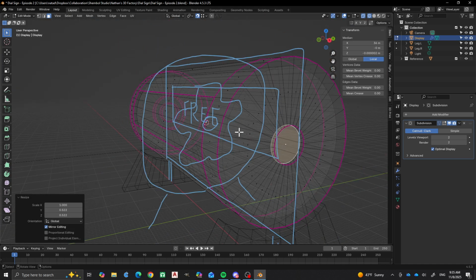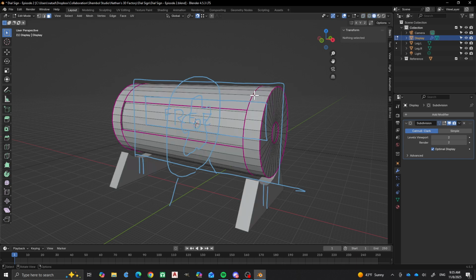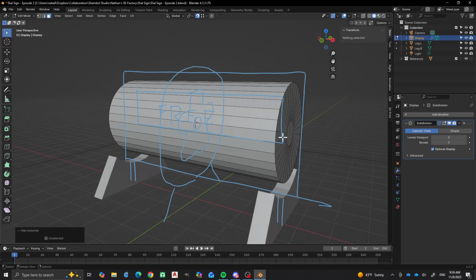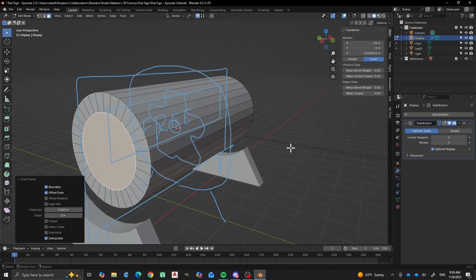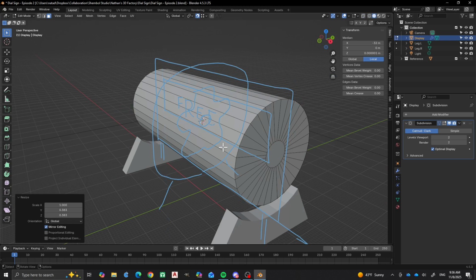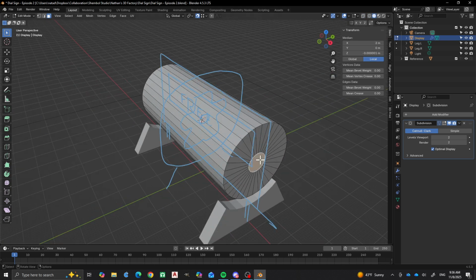All right. So now that we have that whole reference, what we can do is turn off these outside vertices for a moment. Hide that. Inset, doesn't matter how much. S, not X. It'll snap to that. And then what we're going to do is take these two.